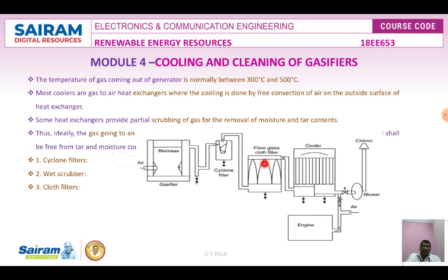Then the remaining gas will be given to the cloth filter. The cloth filter stops any condensation of water and increases the pressure drop, and the pure gas is passed into the engine. So these are the various types of filters used in this process.